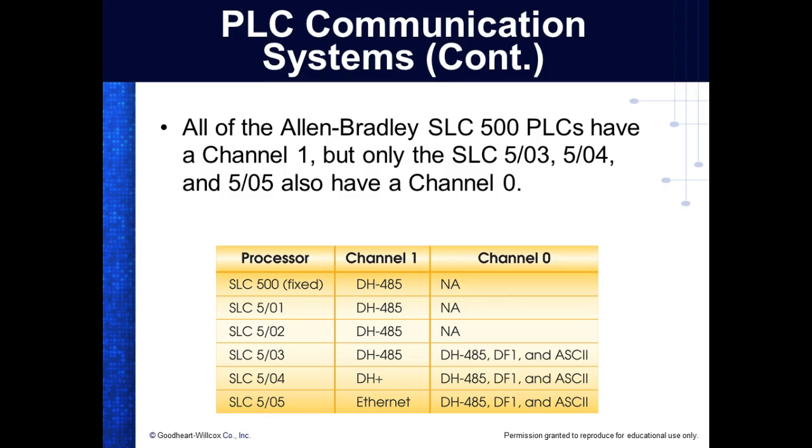Now, if you wanted to use the Data Highway or DeviceNet or Profibus, you would buy a communication module, right? Just stick it on there. But your PLC is going to come with at least one mode of communicating with it and your programming device, right?